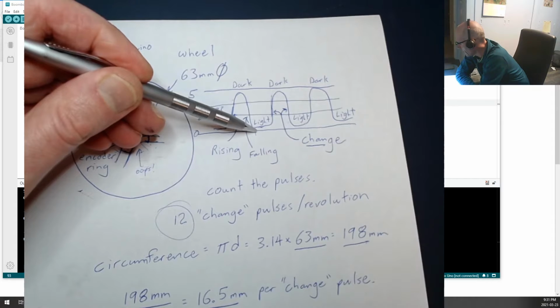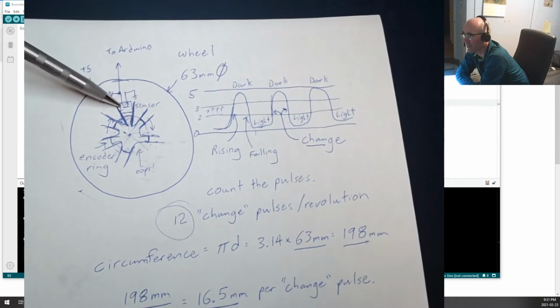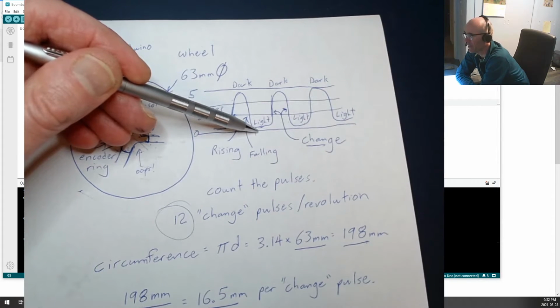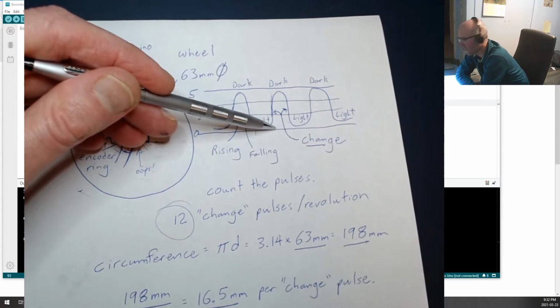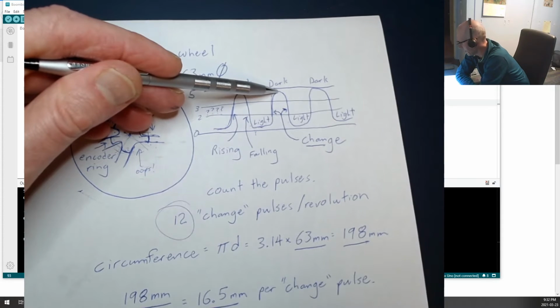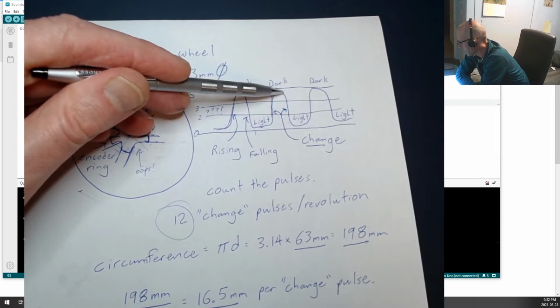Now, we don't go all the way down to 0 volts. There is a little bit of a voltage drop across that phototransistor, but we're low because that voltage drop is a lot lower than the voltage drop you see across the 10K ohm resistor. Now, when there's no light flowing across there, you're going to see that voltage suddenly rise up in here. So when it's dark, it's going to come up high.